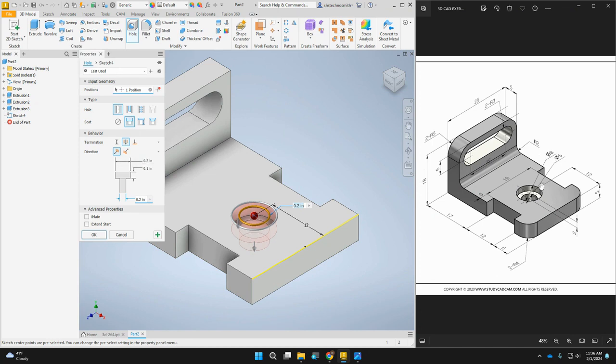So we're going to look at that. Normally a hole is going to be called out slightly different, but we can use what they give us here. We've got a diameter of 8 for the big one, diameter of 5 for the small one, a height of 2, which is between the top circle and the bottom circle. Right. And so depending on what you've used, this is a simple hole that has a counterbore. If you were to imagine what this looked like on the inside, it's got a larger diameter and a smaller diameter.